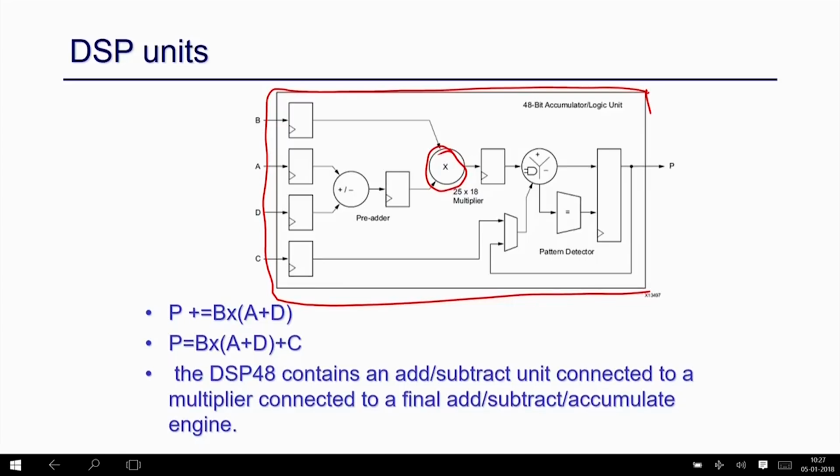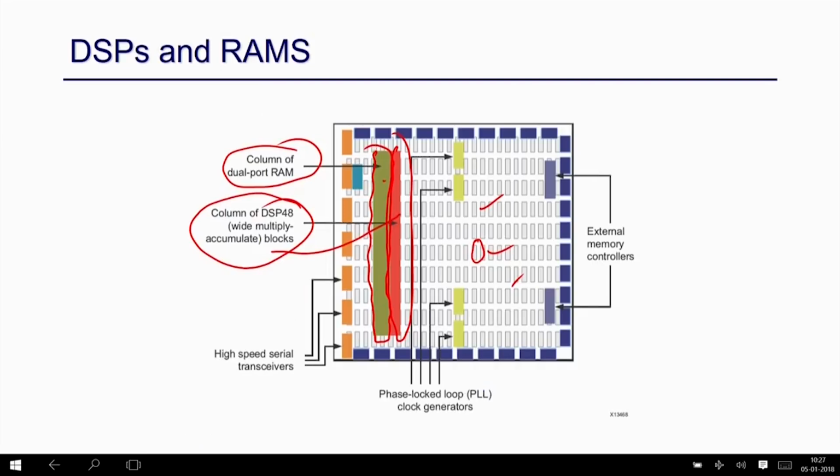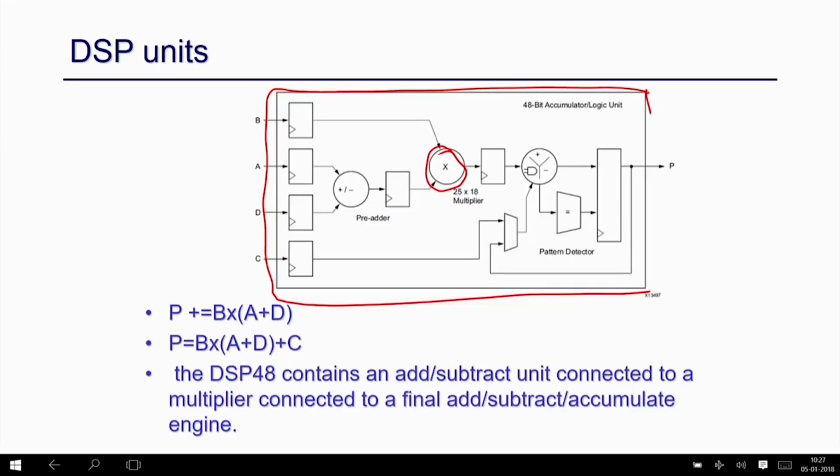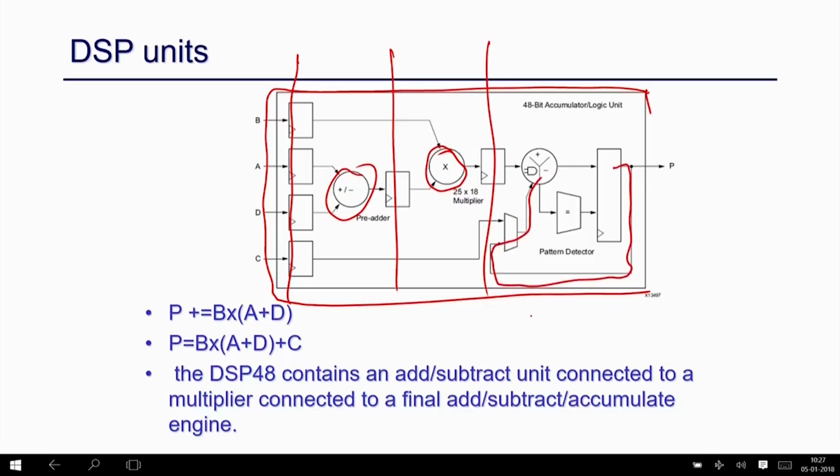If you map a multiplier into a lookup table based design, it will be very big and slow. On the other hand, the DSP is a fast implementation of a multiplier, and it is fabricated within the FPGA board itself. But the DSP unit is not only a multiplier; it can have a pre-adder, and it also has a set of latencies, right. We have 3 sets of latencies here, and this is the MAC. There is a sum, S equal to S plus A, an accumulator, right.